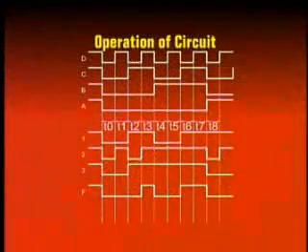The timing diagram describes the operation of the circuit for the product of sum based simplified circuit for the intervals T0 to T8. A, B, C and D are the inputs to the circuit. The timing diagrams show the inputs A, B, C and D changing with time. The timing signals 1, 2 and 3 represent the outputs of the OR gates 1, 2 and 3. The timing signal F represents the output of the circuit.